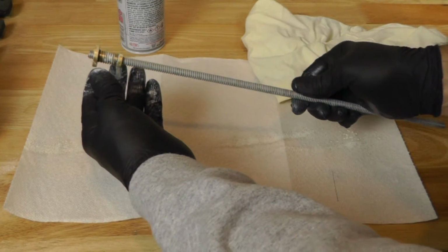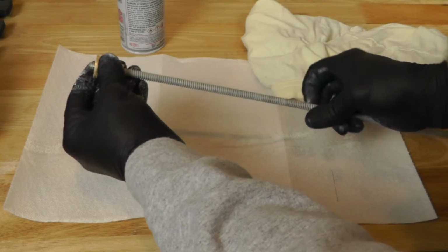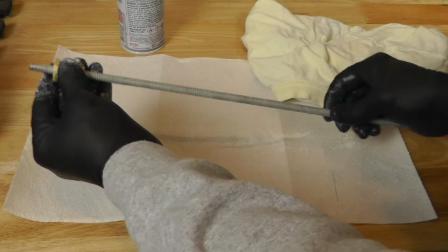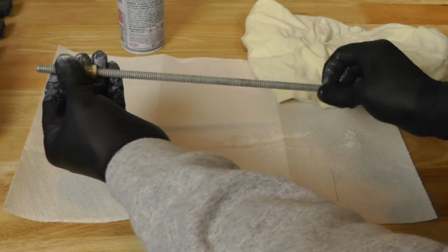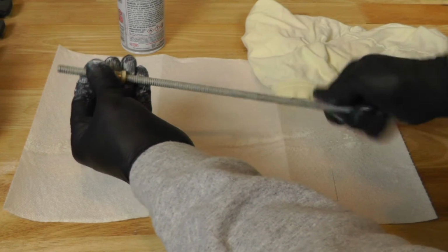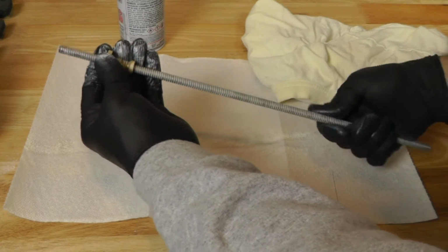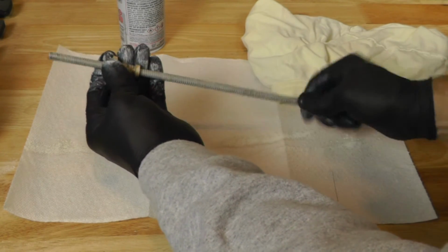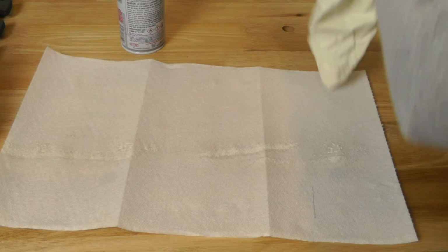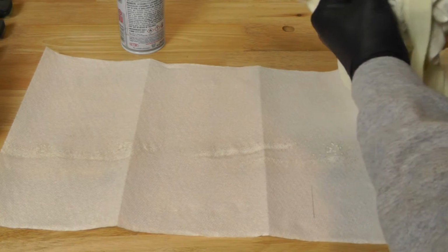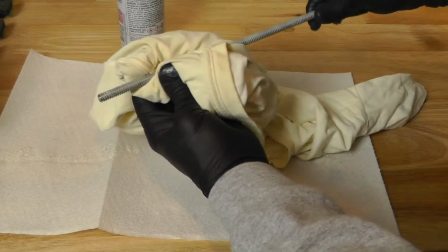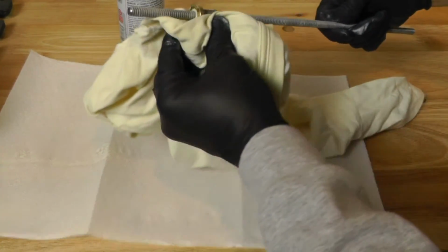Okay, now once you've run that all the way up and down the screw, maybe we should have put this on the other way, but nonetheless, run it all the way back down to a comfortable place where we're going to be able to reattach this to the bed. Obviously, you're not going to be able to reattach it if it's always at the top. And then we'll take our cloth, and I'm going to clean this nut off because we don't need all of this grease on the nut itself.